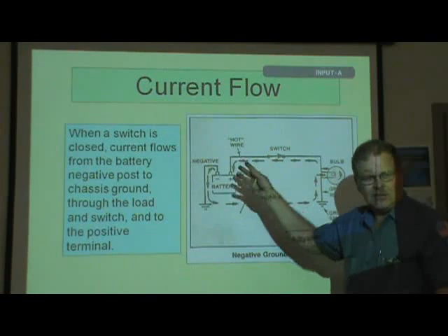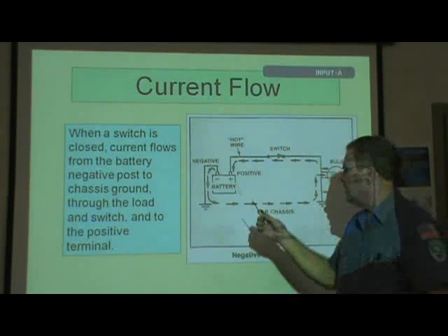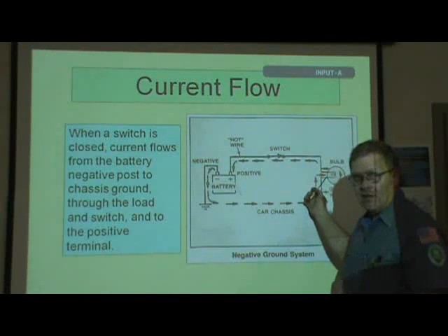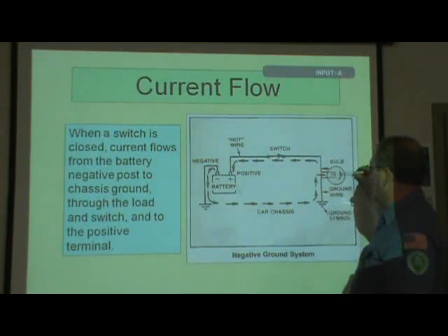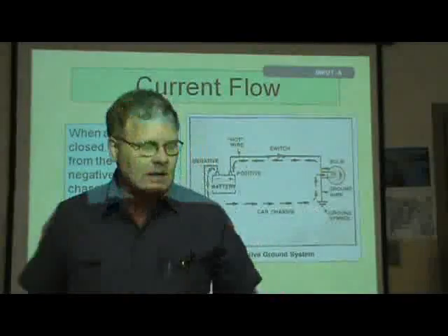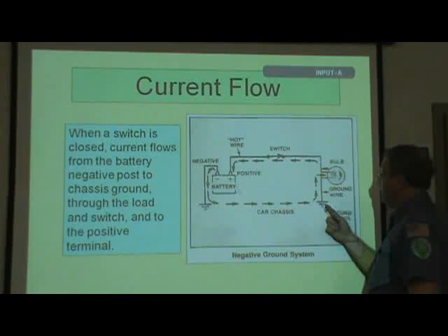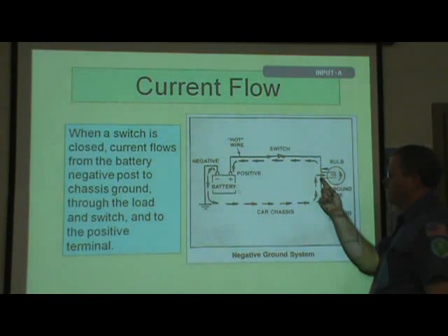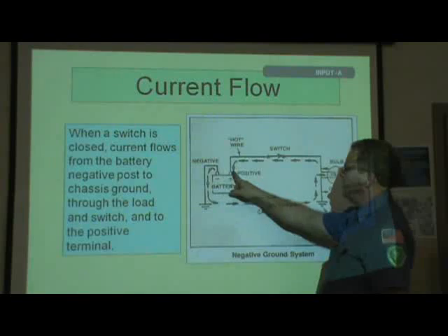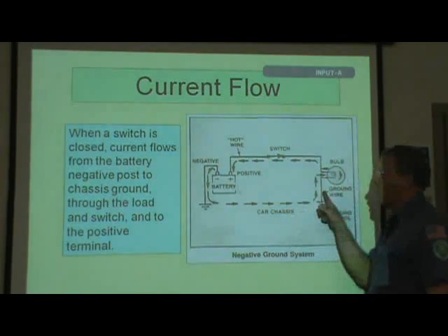Now most of the time, when there's current flowing, if you're dropping voltage, you're going to see some melted place, because heat's going to happen, if it's a load-carrying circuit. The bulb is actually what we would call a load. You can also measure, incidentally, from the negative side of your battery to this side of the bulb, and if you read some voltage drop there, you're allowed to have half a volt here, but you're only allowed to have a tenth of a volt here.